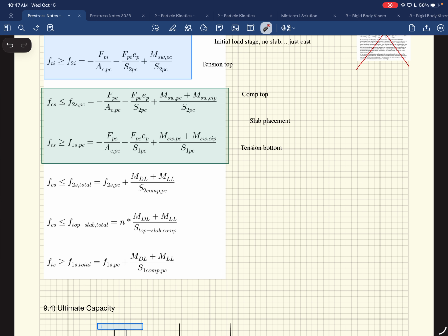It's kind of weird, because I mean, it had to span that whole distance, but it's not spanning it. The beams underneath it are spanning it. And so that concrete on top is just in an unstressed state at this point, because it's wet, and then it hardens from the wet state in an unloaded state. So this is basically the same case as above, except it's reversed.